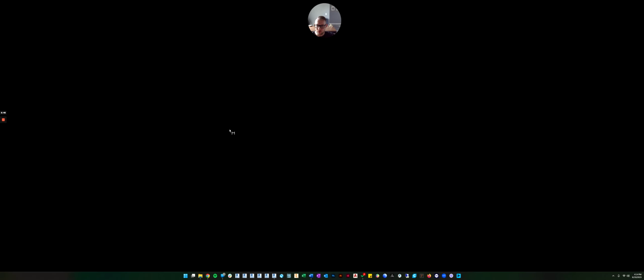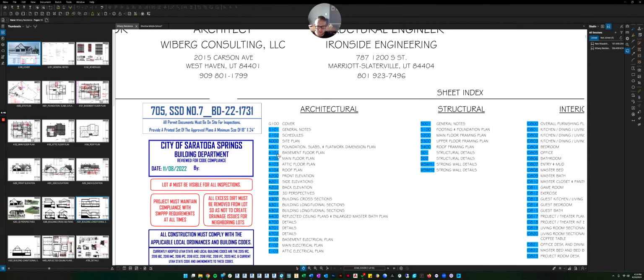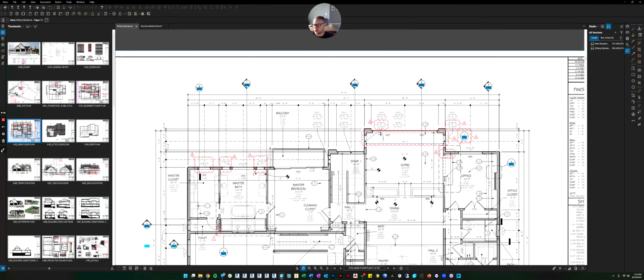So if we look at the example on my drawings, let's go to a floor plan. Typically what happens when you pull a dimension string of the exterior of the building is there's 3 lines, 1, 2, 3, and they get less detailed per line. The first line is really any edge of the building, and then it's also any opening in the building. And again, on a commercial project, if this outside wall was made of masonry, you usually dimension to the edge of the openings, like there.